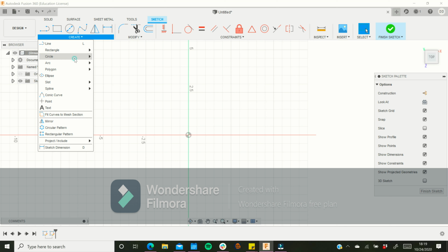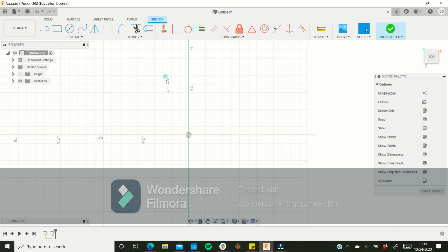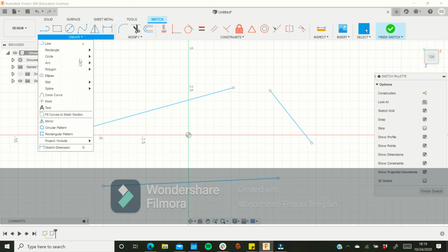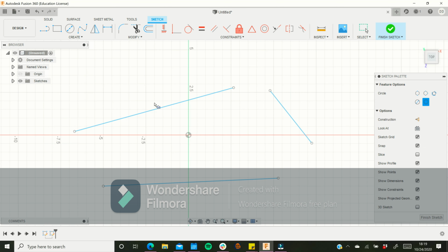So there's a few more circles. These aren't as important, but you got to have some lines to do them. So let's make 2 lines. Actually, let's make 3, because 3 are going to be important at some point. I'll make 1 more, and now I have 3 lines. Let's start by making a circle that is tangent to 2 of the lines. It's just a 2 tangent line circle. You're going to draw it out like this. You're going to click on this line, and then you have a circle that's always going to be tangent to those 2 lines no matter what. You can drag it anywhere, and no matter what, it'll always be tangent to those 2 lines.